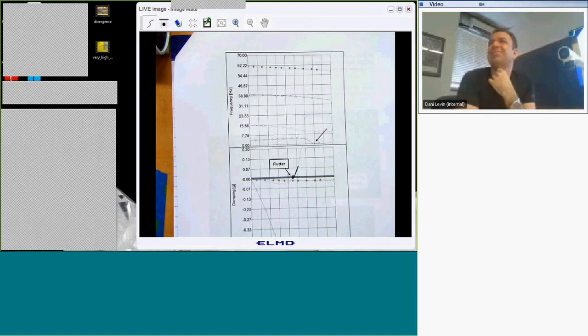So you're able just to see which is the dominant mode, but you don't know which other modes are contributing to that? Oh no, you can. If I go to the flutter point, the flutter condition, that's a certain velocity. It's by definition zero damping, and it has a certain frequency. Then I can go back and look at the eigenvectors of my math model.